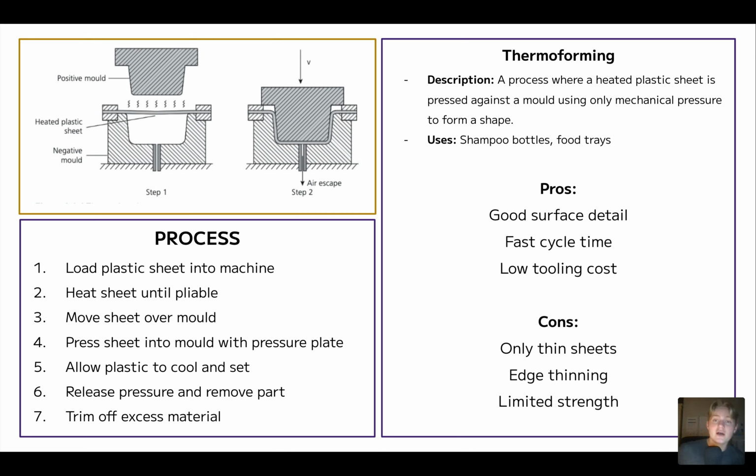So the pros of thermoforming is that obviously you don't need a vacuum, which means there's a lower cost of tooling, because you don't need to create any kind of complex... You don't have to buy a vacuum former. Essentially, you can use basically anything. You could just simply create a thermoforming jig in-house quite simply with a workshop, but it also can give you some great surface detail, which is nice.